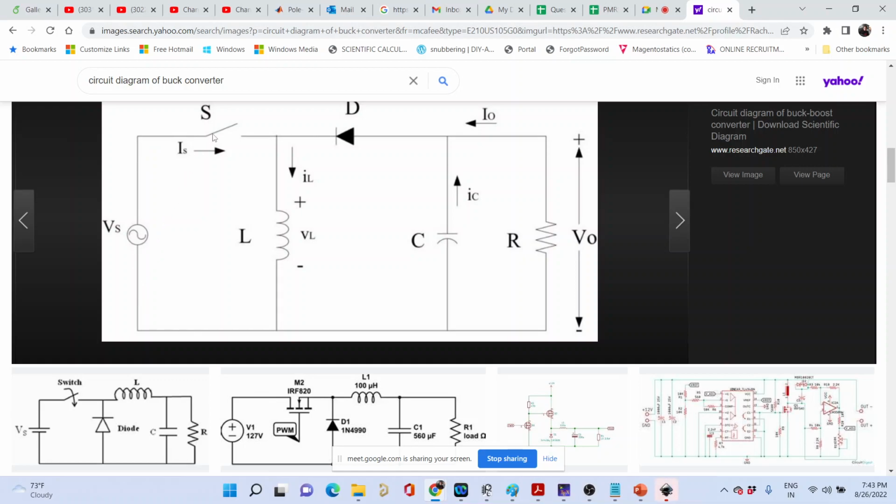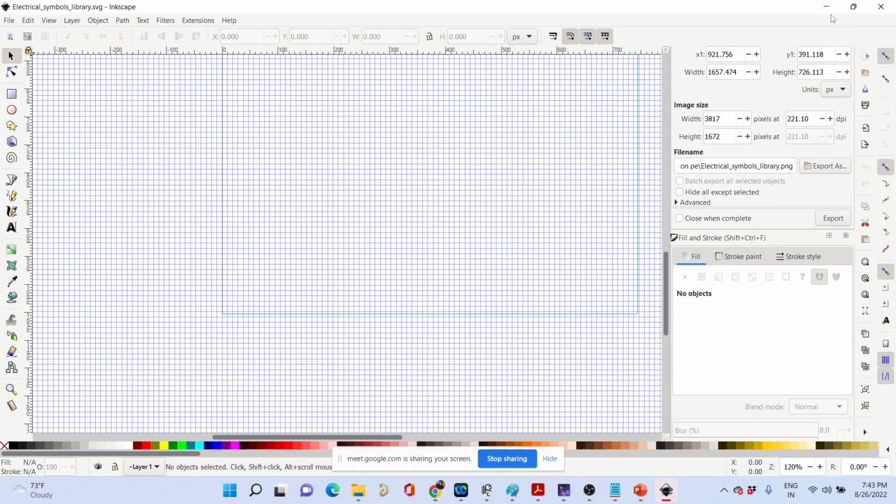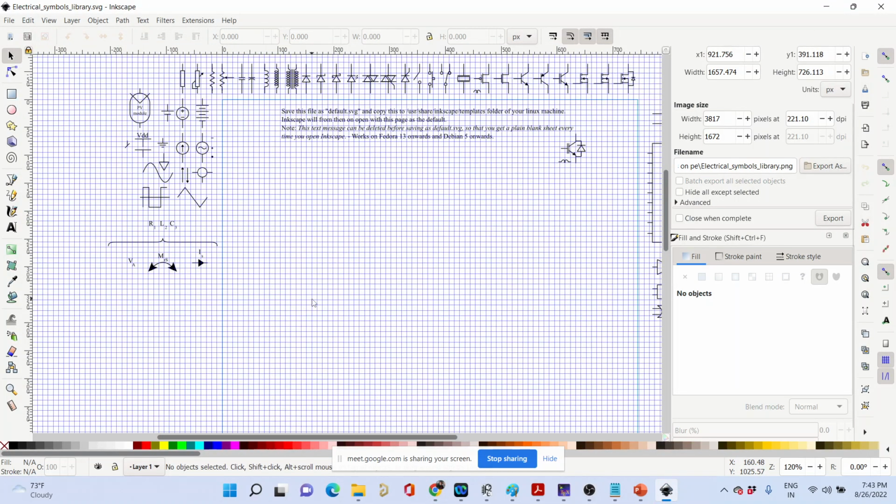If I place a switch over here, then the drain terminal will be over here, the source terminal will be over here, and the gate terminal will be over here. So now these are zero potential, and you are applying 10 volt at this potential. The confusion that we had in the previous case, whether we are actually applying 10 volt or not, is now clear. See, this point is fixed at zero potential now, so I am applying absolutely 10 volt at the gate. Are you getting my point?